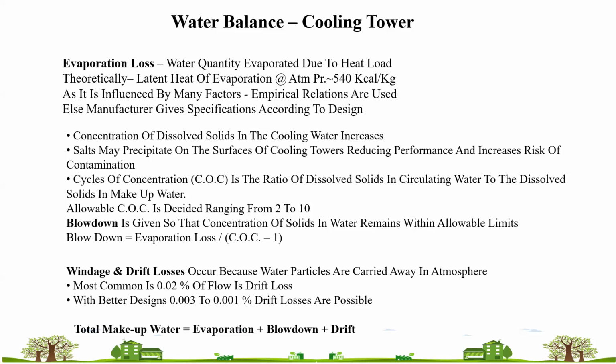This evaporation loss results in lower water quantity. So you need to always make up the evaporation loss, what is evaporating, to maintain the desirable water quantity inside the cooling tower.